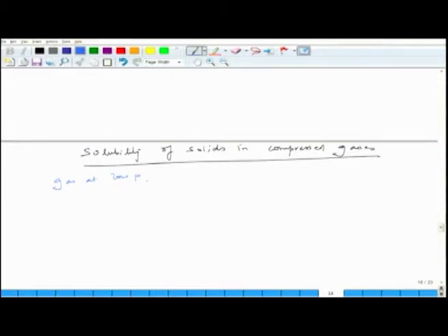But the vapor phase fugacity becomes an important parameter when you consider, let us say, solubility of a solid or high boiling liquid. That means they are very dense, particularly the dense gases. So, if the gas is dense, you have to understand how to get the fugacity coefficient of the gas phase.